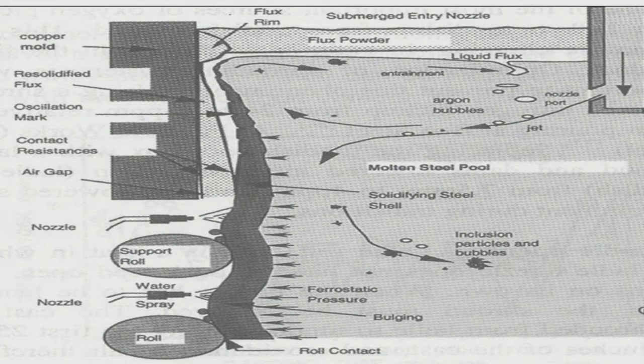Now, after the tundish, when you are using continuous casting, there is a mould. Whether you are casting bloom or billet or slab, whatever it is, there has to be a continuous casting mould. The shape of the mould of course is different depending on what you are casting, but there has to be a mould. What is a mould? Unlike ingot casting, it is an open mould. You see, this is the mould surface, this is made of copper, this is water cooled copper, a copper mould.